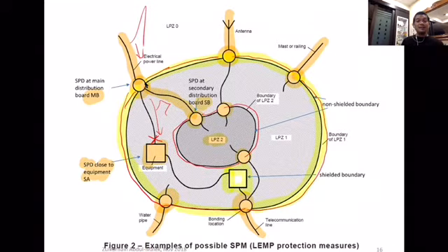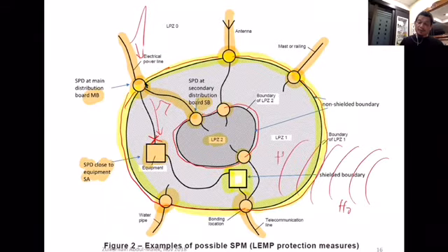That one is actually to shield from the magnetic field. As you know, the magnetic field can travel. So if there's no shielding, it can go in. So H0 here, H0 there also, because there's no shielding. But here it becomes H1, or reduced, because there's shielding at the boundary there. But because we said, okay, we don't worry too much about radiation, only conduction, that's why the zoning here is for conduction.